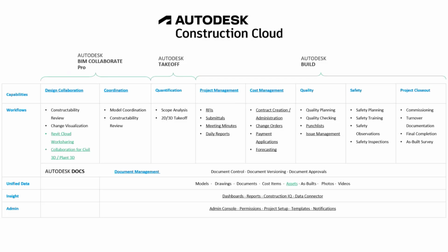You need to set it up by matching the folders and also the models, because once you set that up, you will see the metrics about clash analysis. From there you can see how many clashes there are between architecture and MEP, or architecture and structure, or architecture and civil, depending on how you set it up at the back end before you are using BIM Collaborate Pro.